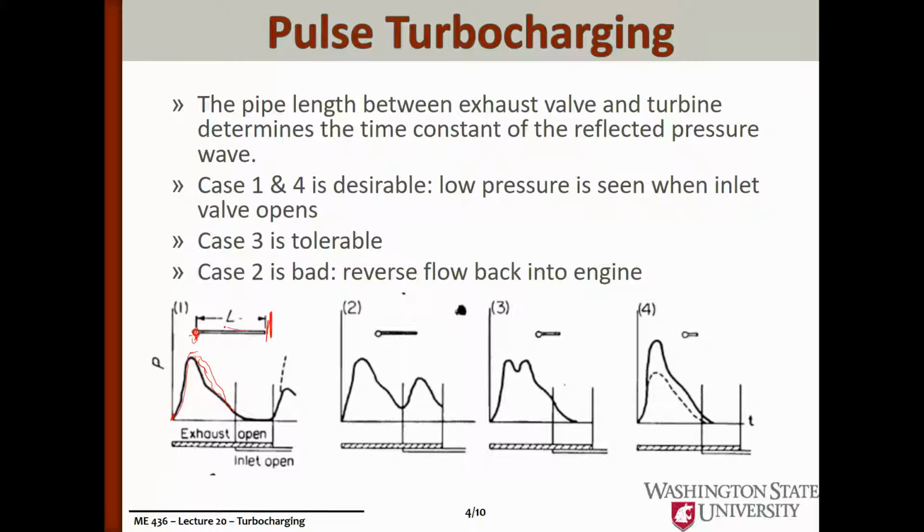And then you get this reflected wave, just like when we were talking about those resonators, and the pressure seen at the exhaust valve when the inlet valve opens is quite low, and hopefully at or below what the incoming fresh air pressure is, because we don't want flow back through that exhaust valve. Now case 4 is an example of a very short exhaust valve tube, and generally works out okay. Similar thing, that the pressure has dropped before the inlet valve opens.